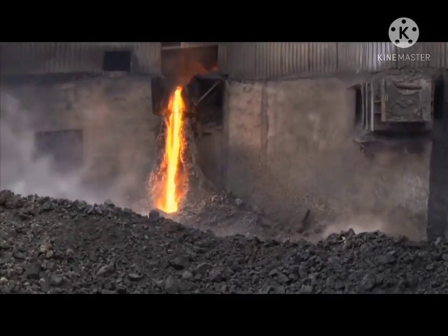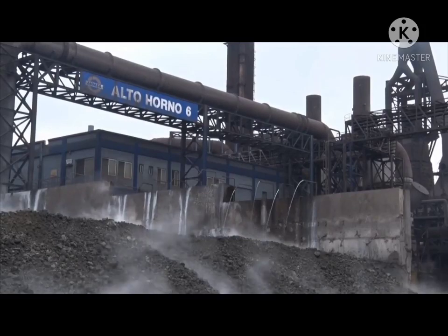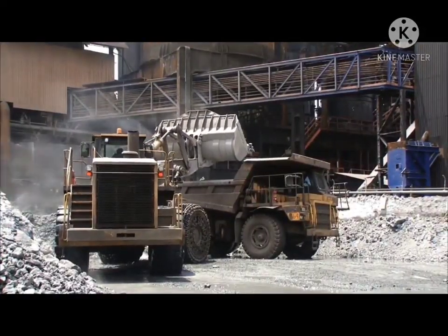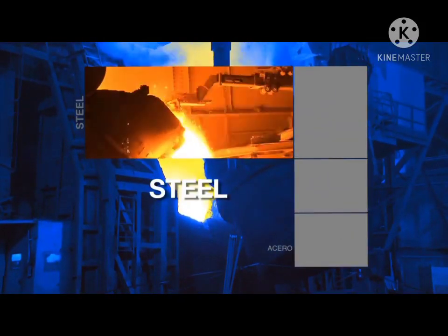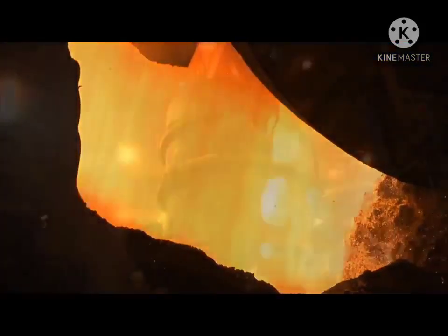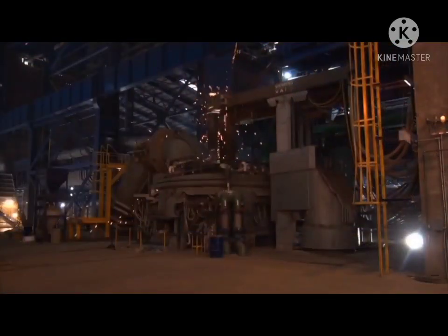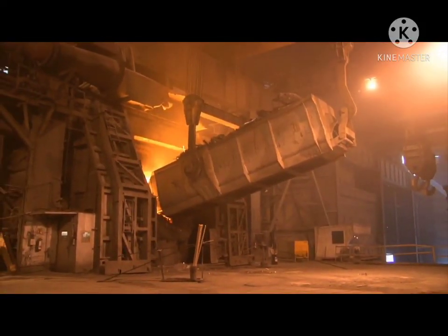In an electric furnace, scrap iron is used and occasionally also sponge iron. Sponge iron is an intermediate product produced from iron ore by means of direct reduction, or DRI, direct reduced iron, and then further reduced and smelted in the electric furnace.